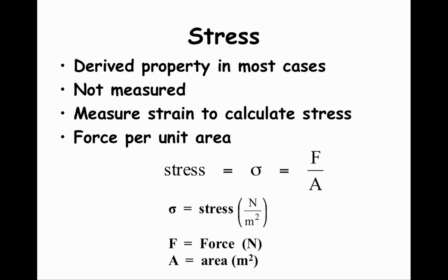Stress is defined as the force per unit area applied to a member. Stress is usually not measured. We will measure strain and calculate stress using Young's modulus of elasticity. Stress is commonly described using the lowercase sigma symbol, and stress equals the force per unit area.